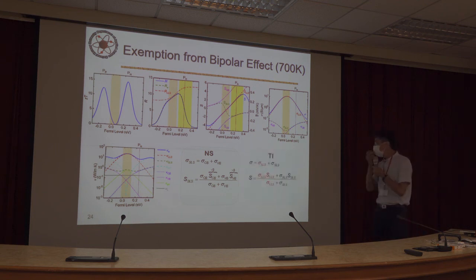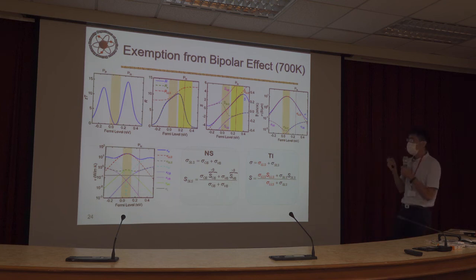For topological insulator nanostructures, the in-gap topological edge states are incorporated. The long lifetime state conductivity can overwhelm the short lifetime state conductivity. So the feedback coefficient is nearly equal to the long lifetime feedback coefficient. So the bipolar effect does almost no harm to the feedback coefficient.